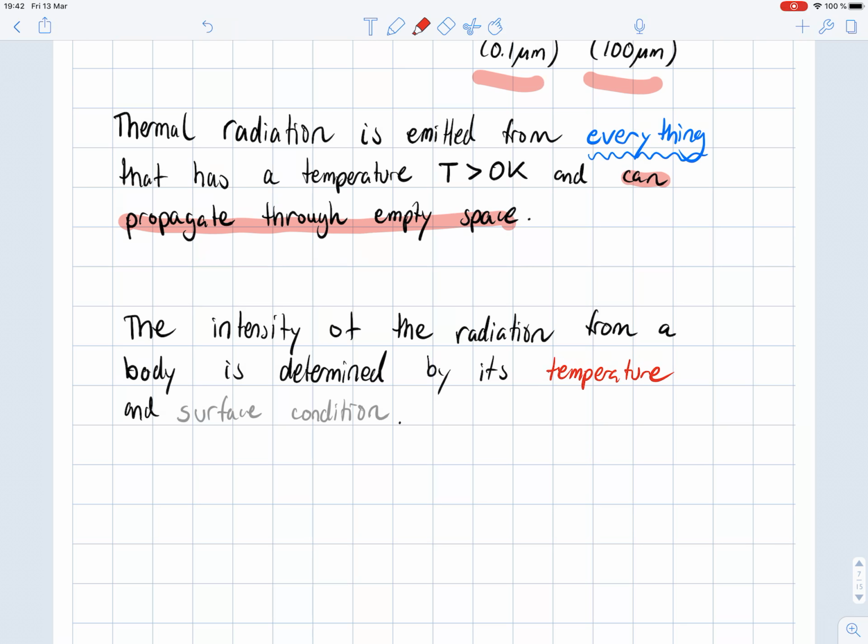An interesting feature about thermal radiation is that its intensity is determined by its temperature and thus condition of the surface, so the surface condition. So these two properties are of prime interest. And of course, surface conditions themselves are also something that we can control when we produce our metals. So this is sort of a two-way effect. The surface condition itself controls the radiative properties, but if we are able to control the surface properties, we can of course make the surface radiate as we want as well.